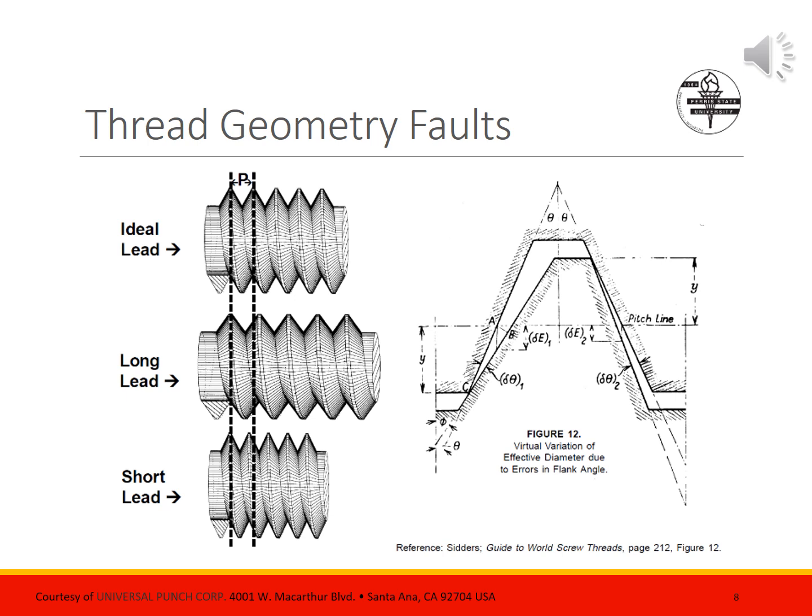The top sketch on the left depicts the thread pitch desired. You can see the lower two sketches, the long and short thread pitch, they're out of whack, right? Both of these failures will be detected by a thread gauge.